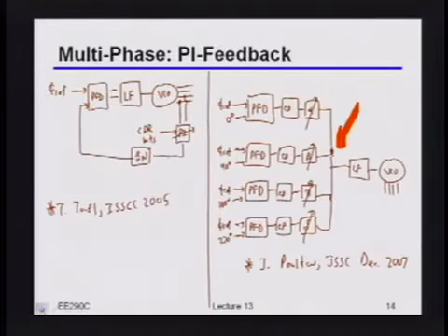Oh, yeah, follow-up question. If you compare the two of them, then I guess a good trade-off is the first one? Yeah, this is a pretty reasonable thing to do. It depends on what context you're in, how much multiplication you need, and what the reference is. But this is a fairly reasonable approach as well, and people are using these kinds of things. Although it's also heavily dependent upon how much multiplexing you're doing in the first place. If you're not doing very heavy multiplexing, for example a full rate system, then there's no difference between doing this and just having the phase interpolator open loop to begin with.